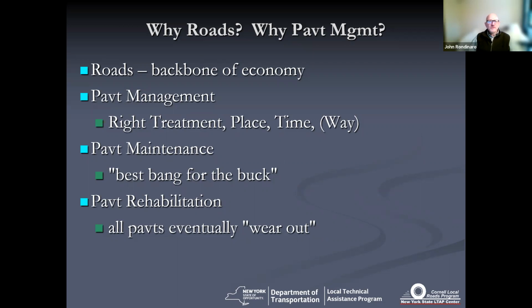Within that pavement management framework, we focus on a pavement maintenance strategy. That's where you're focusing on low-cost treatments to keep your good roads in good shape, and you do that because you're getting the best bang for the buck. But regardless of how good your maintenance strategy is, eventually all your pavements are going to wear out. Nothing lasts forever. They're going to lose their structural integrity. They're going to lose their load carrying capacity, and you've got to do something in terms of pavement rehab to get them back into a like new condition.